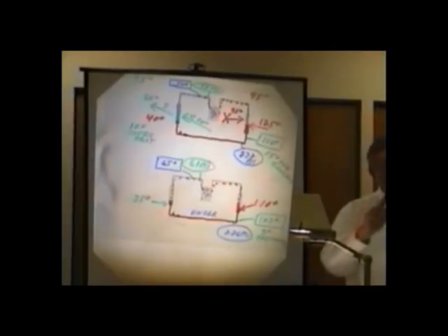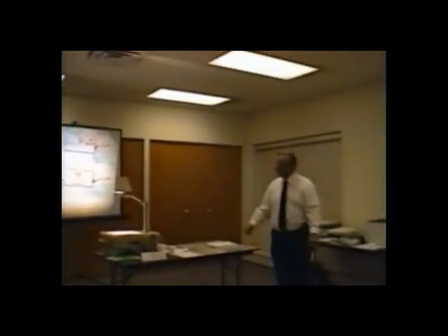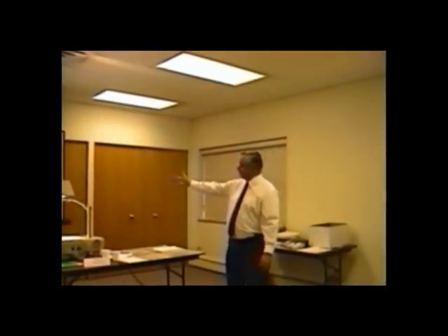However, I come over here now and I put my thermometer on here and I have a 65 degree suction line. How many degrees warmer is my suction line than my evaporator? 30. I have 30 degrees of superheat. We know that the superheat changes, but I certainly don't want 30. When we start looking at a superheat charge, I better have about 5 degrees, according to a superheat chart.